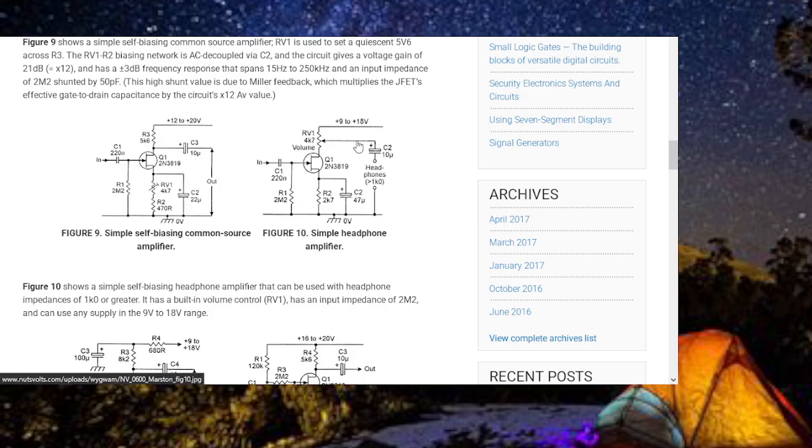My idea is to take the 3819 and get a gain out of it. They said you want to filter, put the filter first and then amplify. There's kind of a filter there. And we can run the circuit program now, since I got that fixed, and run some AC analysis with a 2N4416.